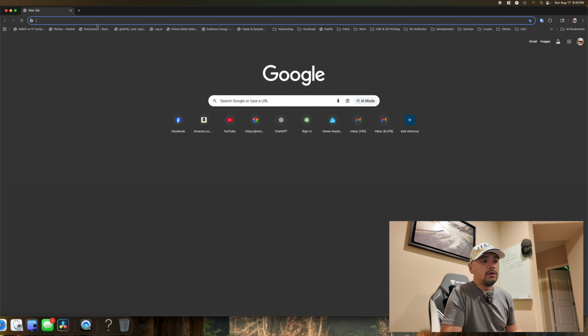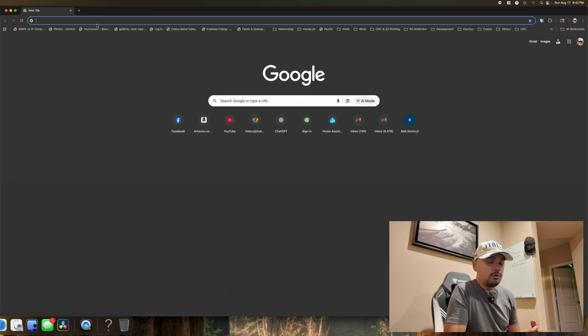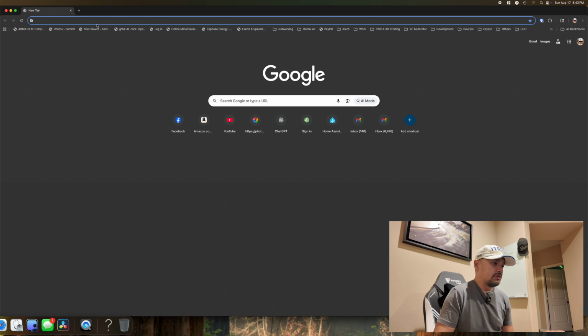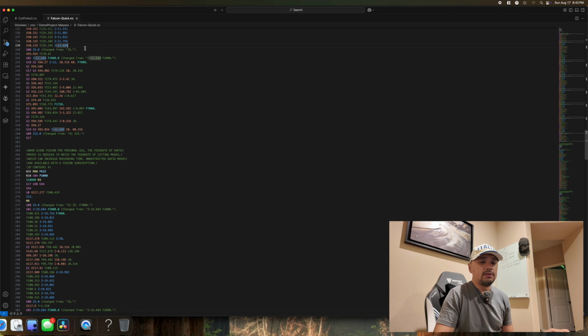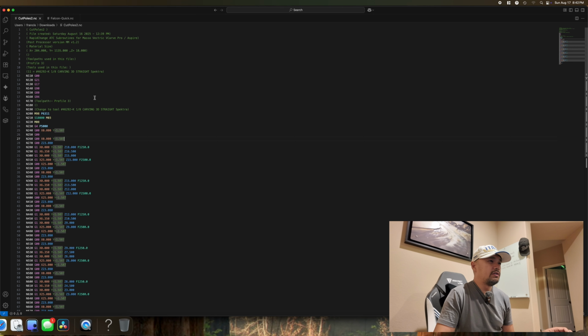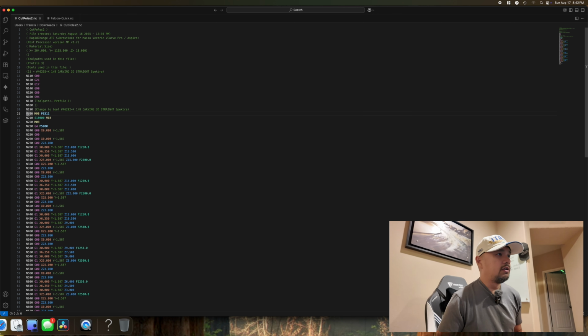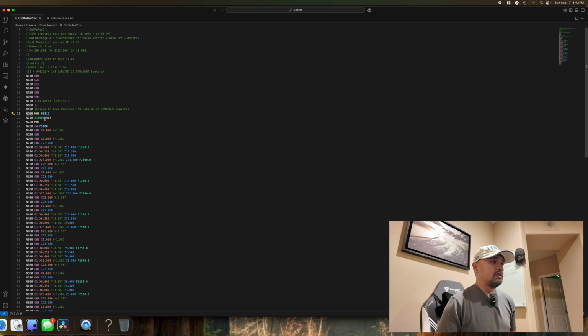Now the idea is we want to retract the AutoDustBoot during the tool change. If you're using the post processor of Vectric or whatever RapidChangeATC provided you, open the G code. For example, I'll show it to you. I have one G code here that my customer provided. If you look in here, there's N200, which is line 21. I believe the post processor for Masso always inserts line numbers, so N200 is a reference.